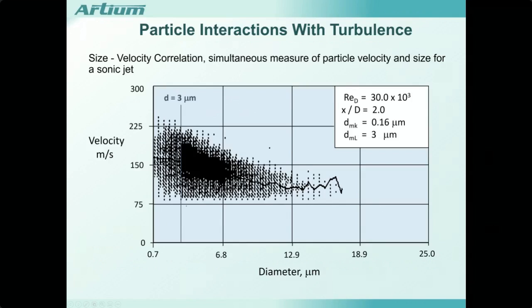The collection of samples has a high population here because that was the kind of size distribution of the atomizer that we used. And that's the point I made earlier, that you have to be careful when you claim a certain size for an atomizer. You may have a large population of relatively small drops, but you're going to have some large drops out on the tail, and those may be the ones you're measuring.